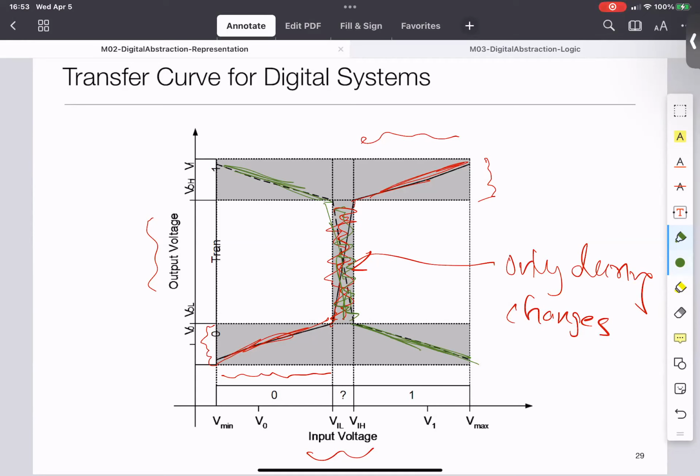You are not going to stay there, because while you are in there, the system is neither 0 nor 1. It's just some analog voltage value. And as I answered a few moments ago, if the circuit outputs this value on a permanent basis, other than this tiny amount of time, then the circuit has suddenly gone into a non-digital mode, and you can't do anything about it.